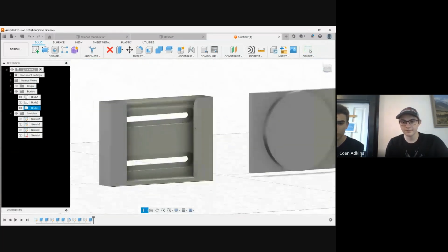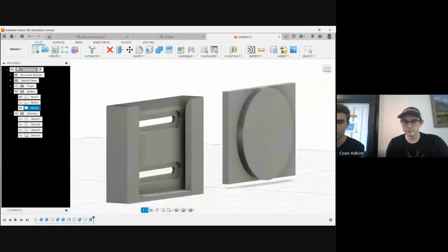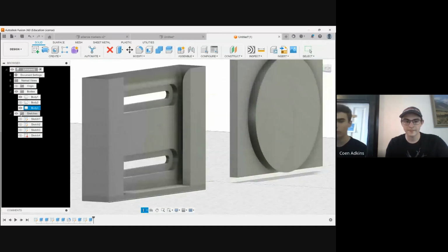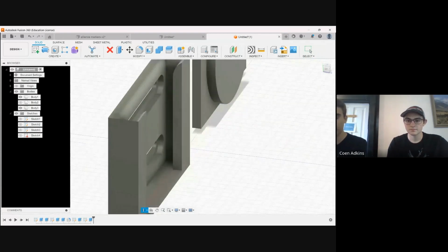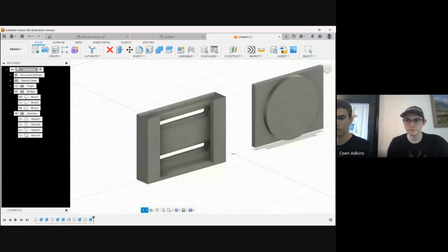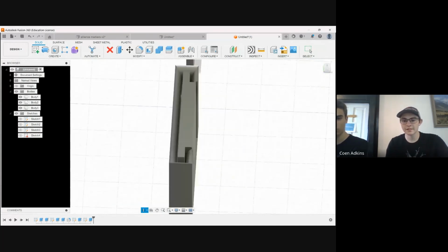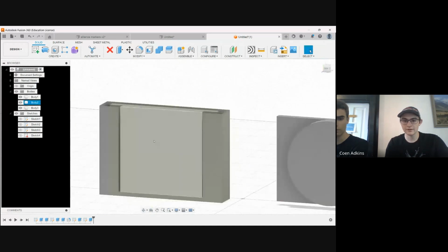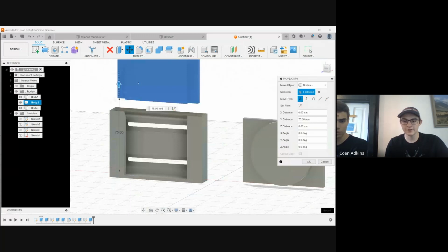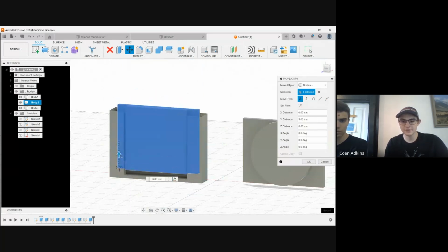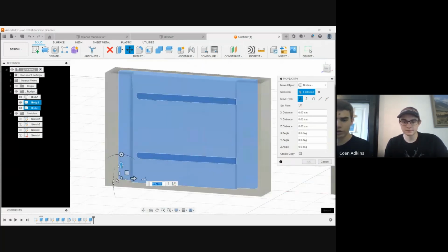And so now that leaves you room to have the head of your screw in there without the alliance marker running into it. Depending on which screws you are using, you'll need to adjust the depth of that. But for the Rev screws, which is what we use, 3 millimeters works. And now this should be pretty much the finalized part. To show a little example, you can move it in and out, and it should perfectly fit into the part. That'll work the same way with the circle alliance marker as well.